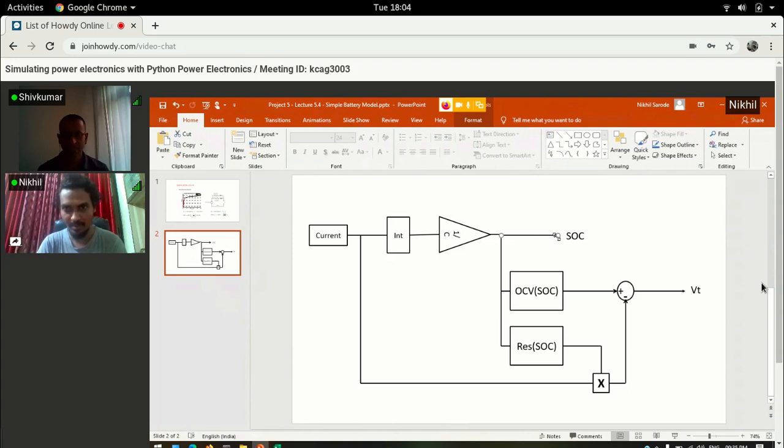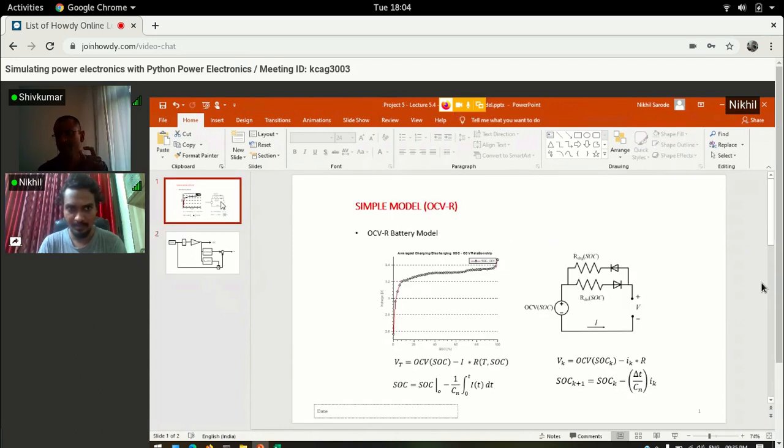So here you are saying that I should put a summer and take an input of initial charge. Yeah, and also the current has to be negative, because the convention we are using is that this current is a discharging current. So if we start with a battery that is completely uncharged, then any current that the battery draws will result in the charge gradually accumulating.